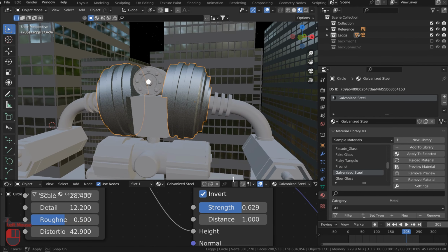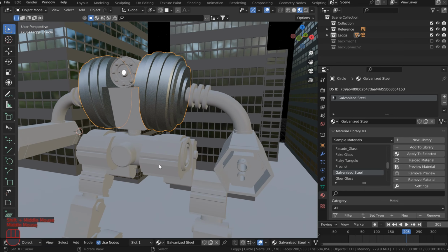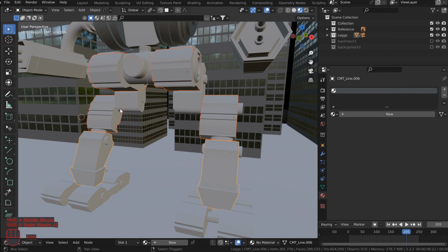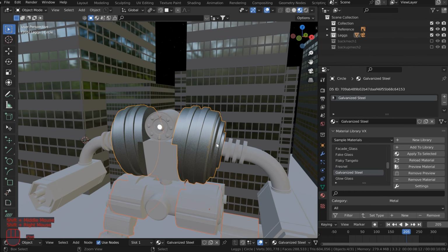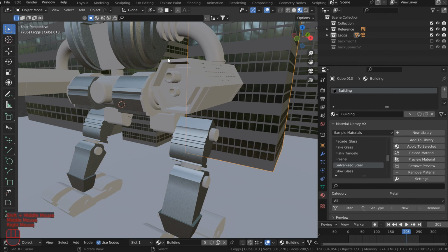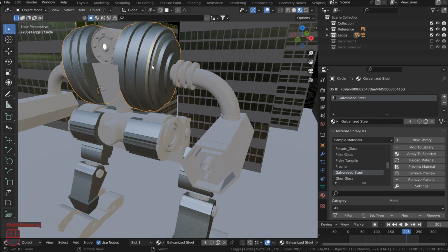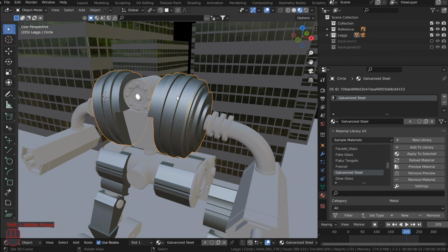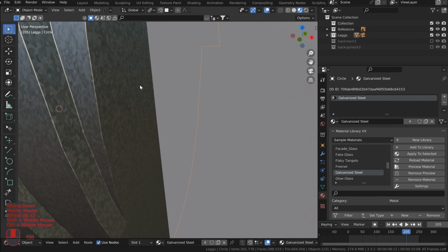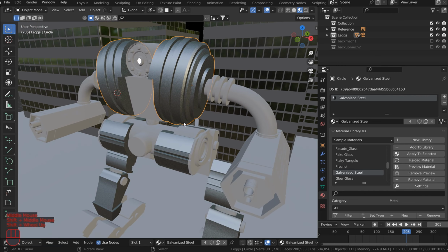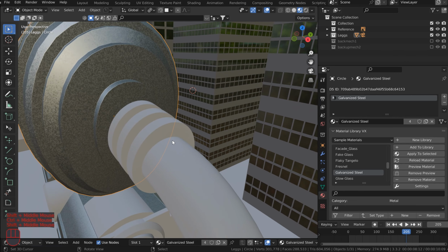And so now you could technically leave it that color and that type of shader, and then you could go through and just right click and then Control L, link those materials, and then that'll work for a bunch of these, and you can have a nice two-tone battle mech. That could actually use an overlay, and I may do a separate video. In fact, I'm more than likely going to do a separate video with Philogix PBR Painter Pro, so that way those users can go in and I'll show you guys how to make some really cool textures, and we'll kind of play around with the AO so that rust, paint chips, and things like that will end up in the occluded areas. That would be the AO.